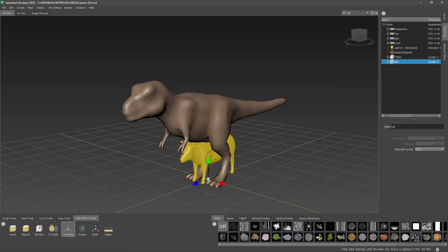So you need to be careful about orientation, especially when you import from other software. But right now we don't care about that. We're going to talk about importing later. You can see here I'm clicking on the red arrow and I'm just dragging with my left mouse, and I can move also by clicking on the blue arrow and dragging again with the left mouse. Same thing with the green arrow, which means that I'm moving things in one dimension only.